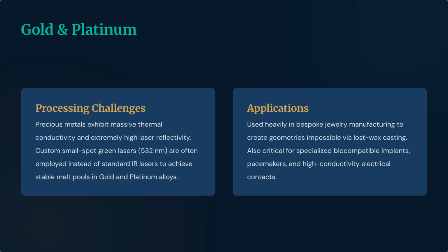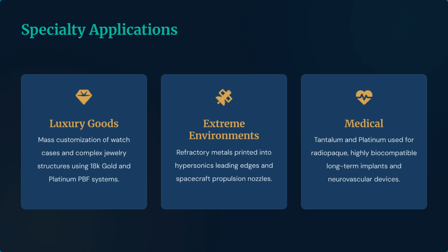Precious metals like gold and platinum present challenges due to high reflectivity and thermal conductivity, often requiring specialized green lasers to ensure stable melt pools. These specialty materials have diverse applications, from luxury watch cases and bespoke jewelry to critical medical implants and aerospace components.